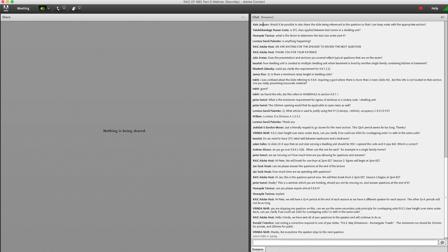So sentence 5 is the exception to this, and I believe what your question is related to. Where the window does not require the protection of that previous sentence 4, where the window serves a dwelling unit that is not above another suite, or the window serves a house with a secondary suite. And then there are other exceptions to that.